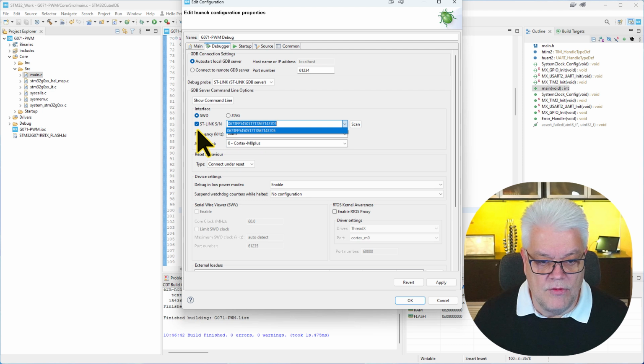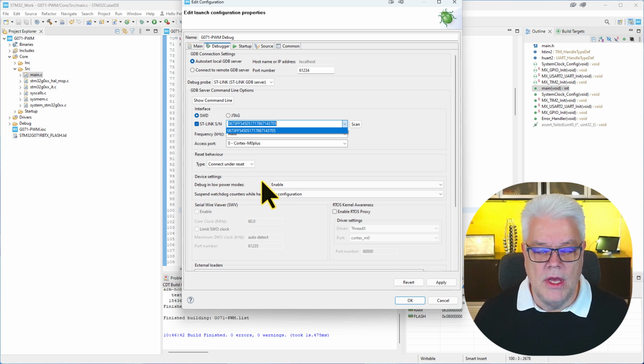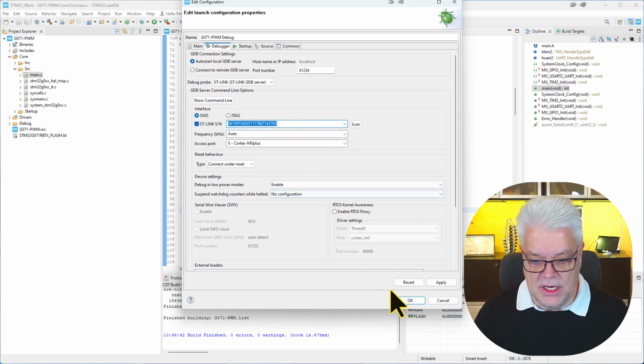If we have several boards connected to our application, we can actually see several of these. So we can have more than one. That is a question I got before: can you actually have more than one debugging? If you, for instance, have one that you would like to send data from one microcontroller to another microcontroller, can you have two simultaneously debugging? And yes, you can. You need then to change which debugger you would like to talk to in which session. In this case, I only have one, so I select that one.